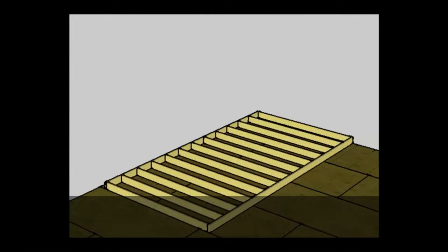So once we have our platform in place, now the framing contractor has a good surface to work from to start building those support walls that we talked about. Those support walls are going to be comprised of 3 basic elements: a bottom plate and a top plate, which you see here, and those are going to create the horizontal extents of the wall system. Within the confines of the bottom plate and the top plate are going to go what's called the studs that you see here, and the studs are going to be fastened to the bottom plate and top plate, typically using nails. The studs will create the vertical support and also the vertical limits of the wall height.